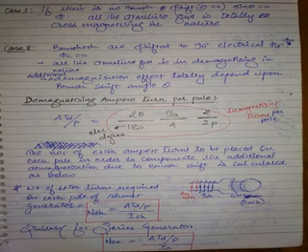Then you place 2 brushes. So if there is IA here, what is the current in this? IA by 2, IA by 2. 2 parallel paths, IA by 2, IA by 2. If there are 4 parallel paths, IA by 4, IA by 4. Let us make it generally, let there be A number of parallel paths. So what is the current flowing in the turns? IA by A. Why you have to write this: here there is a turn known as ampere turn.